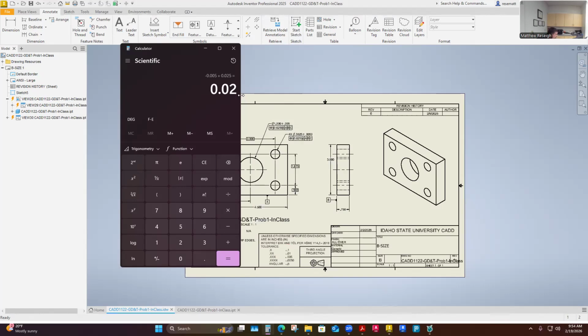Your book also shows that if you have an internal feature for positional tolerance, there's a little formula: actual size, meaning the actual part size as measured and inspected, minus the MMC, plus the specified positional tolerance, equals the applied positional tolerance. So I may have gone the wrong way, and our tolerance zone may have diminished to 0.02 rather than 0.03. So I'll think about that.